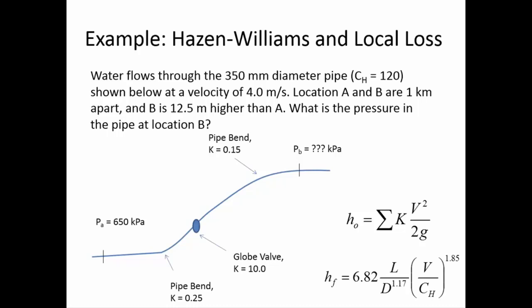What about the alpha that's in front of the velocity head term? It's a coefficient of some sort, definitely. It's the kinetic energy correction coefficient, and it is related to the velocity distribution. If you had laminar conditions, then the velocity profile is bullet-shaped like this.